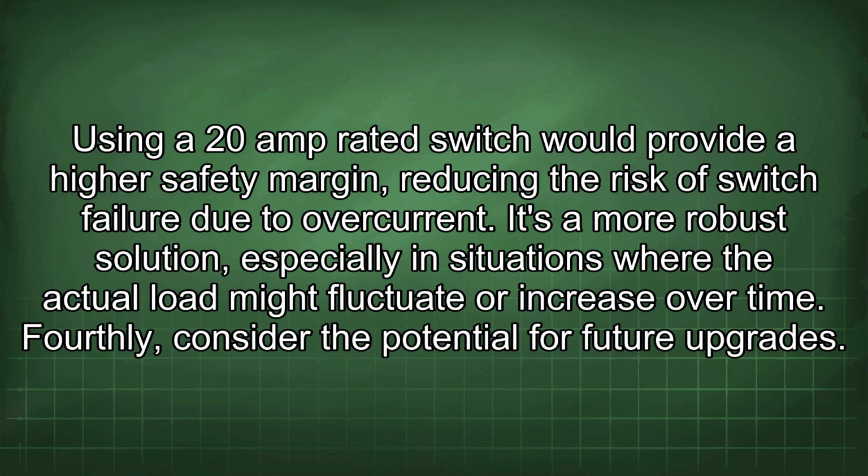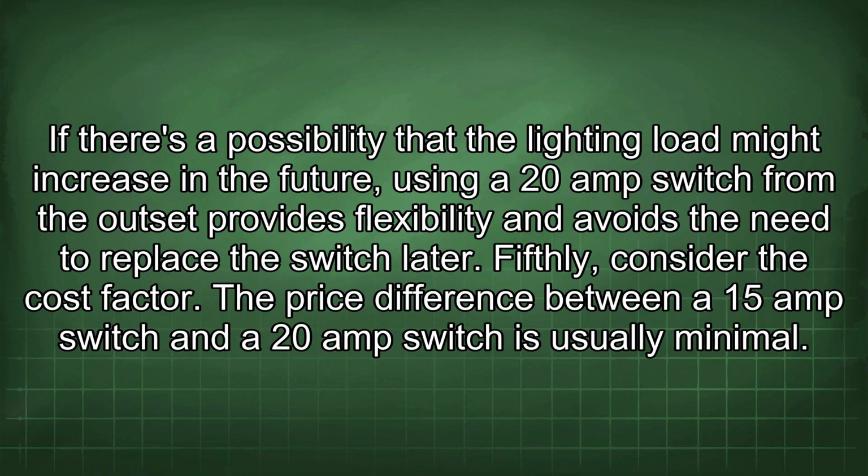Fourthly, consider the potential for future upgrades. If there's a possibility that the lighting load might increase in the future, using a 20 amp switch from the outset provides flexibility and avoids the need to replace the switch later.